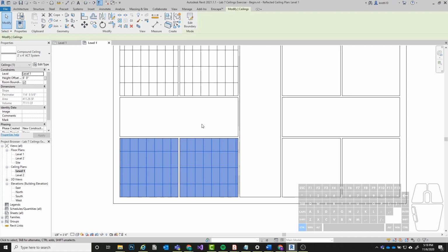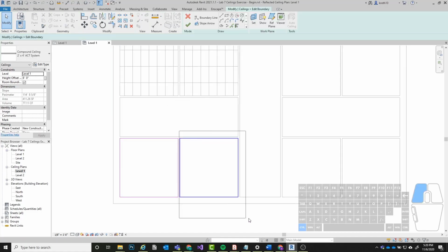That's not great just in terms of controlling them. Let's say one room I wanted the ceiling to be one height, and in the other room I wanted it to be a different height. With it connected like this, you won't be able to do that. Whenever you switch the height, it's going to control it in both rooms at the same time. So what you really want to do is draw them individually if you were using the sketch option.